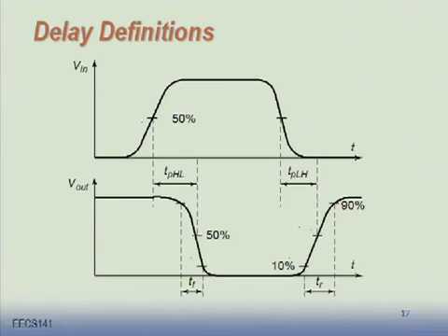We put registers at the end, something that you might have seen in CS61C. Find that path and find out what is the maximum frequency that we can run that path. Remember, we would like to run these things at a few gigahertz if we can. So it's very important to know what is the propagation delay of each of these gates.